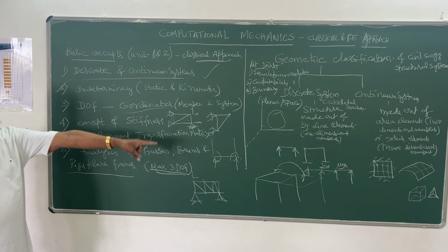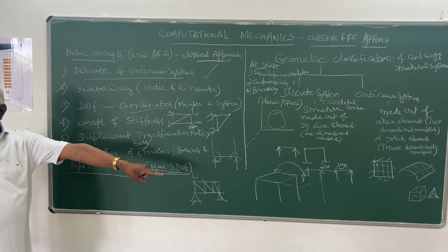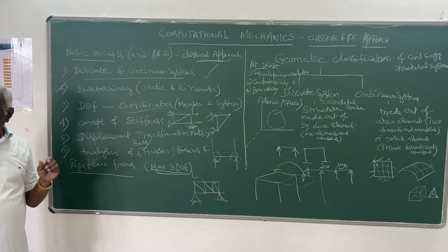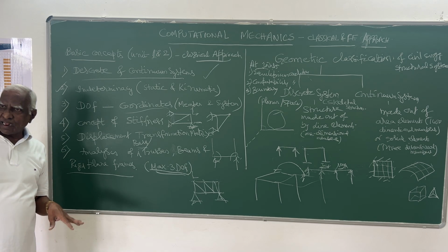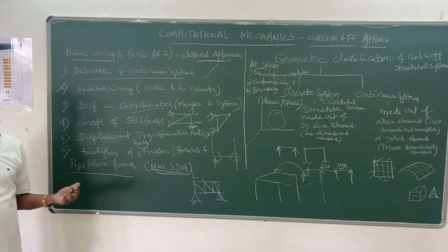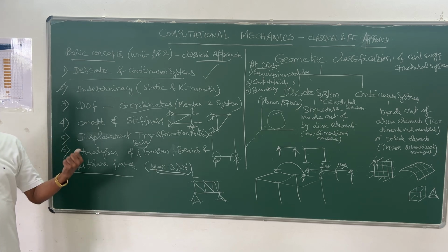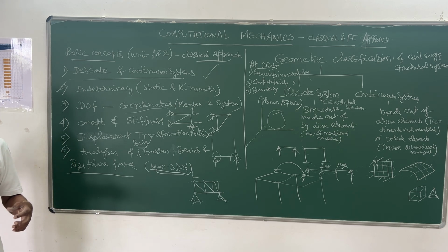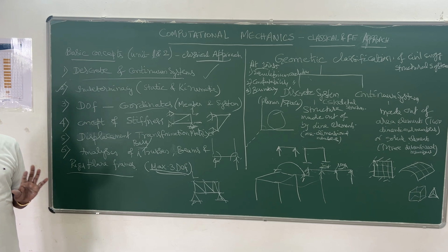After this, understanding the type of structure and where we have to determine these unknowns, what you have to do in analysis. In analysis, we have to determine internal forces developed at the joints, that is at the ends of the members, as well as reactions developed at the supports. That is with respect to forces.